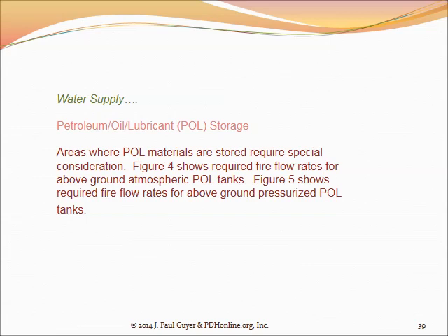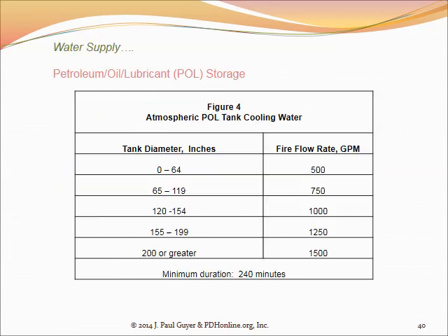But again, whatever you have to do with your building is going to be dictated by your local building department and fire department. For non-building application or installations, again, this is Department of Defense stuff, talking about petroleum oil storage facilities, oil tanks, gas tanks, things like that. The fire flow required depends upon the diameter of the tank, ranging from 500 to 1,500 GPM, and the duration required is 240 minutes.